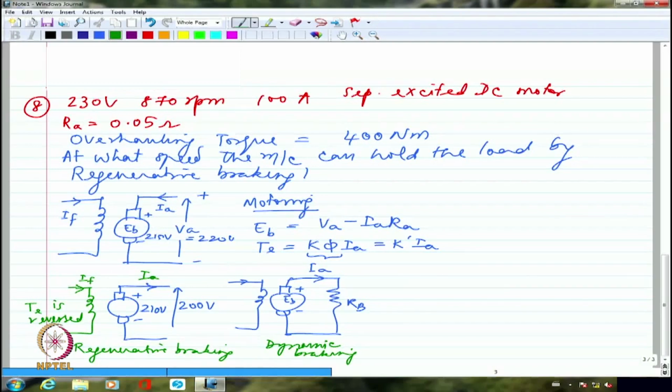If you are talking about quick stopping, maybe that gives a quick stop, that's what you think. But here also if I put a small resistance, it will give me very good stopping control. Electrical braking gives you extremely fine control. That's why electric vehicles generally have an excellent braking mechanism, if it is designed properly, of course. So this is regenerative braking.